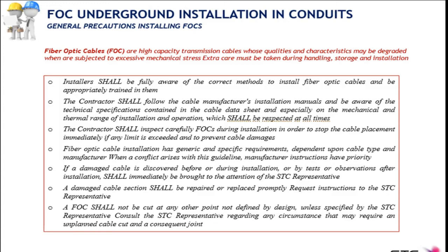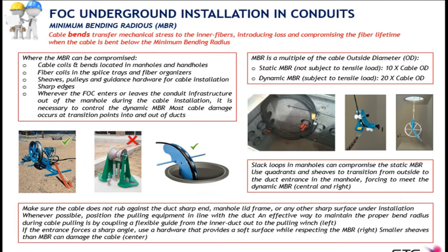They are very fragile. So you have to be aware of that when you operate all these elements, cables and ODM components. And always read and follow the manufacturer installation manuals. Now we are going to see additional parameters that have to be taken into account while installing fiber cables.